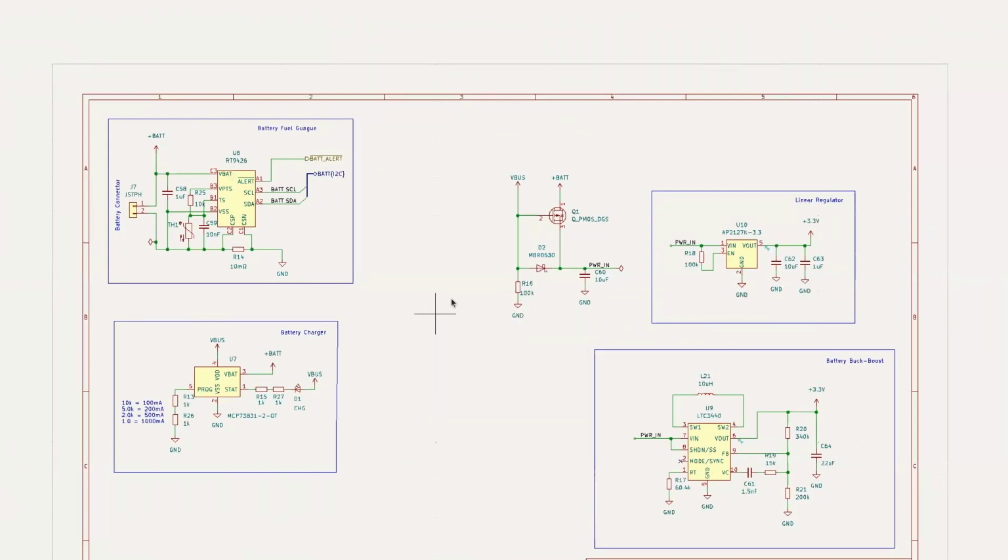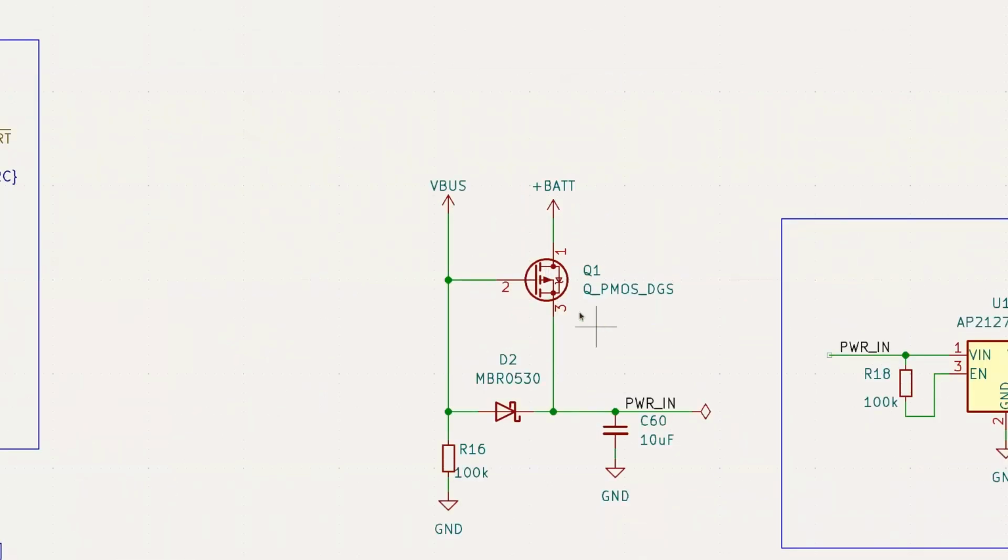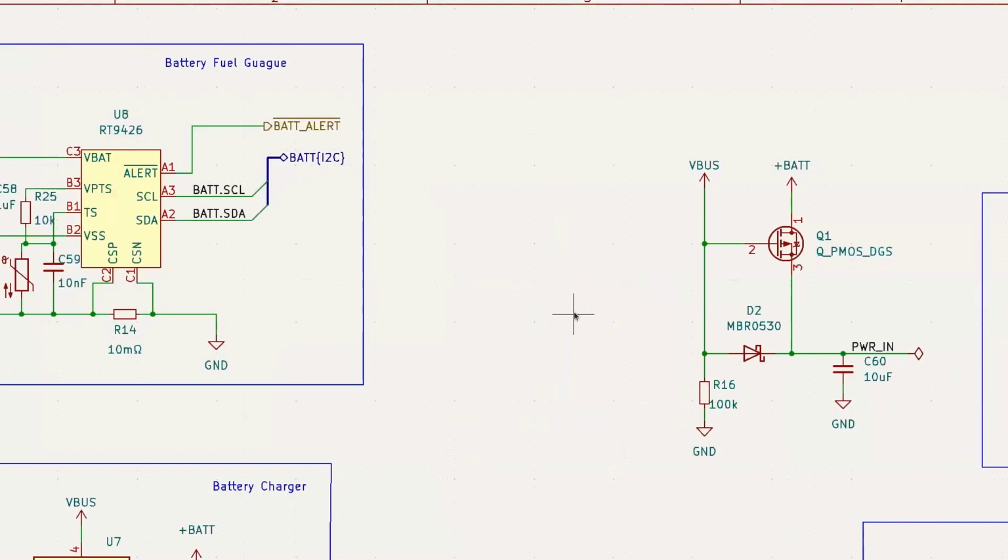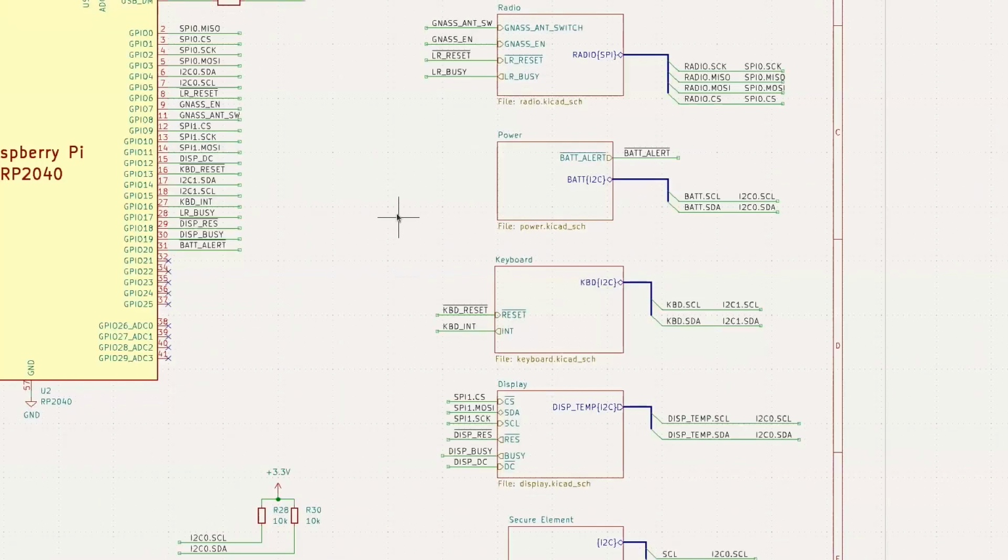So you could actually do that with diodes. You could make that with like 3 or 4, let's see, 4 diodes. And by using a P MOSFET here, it's less lossy, right? Exactly. It's less circulating transient currents, but the diodes will get it done if you need to go plain and simple. It's effectively the same, not ideal circuit. Yeah, for sure. Okay, we might as well go through.